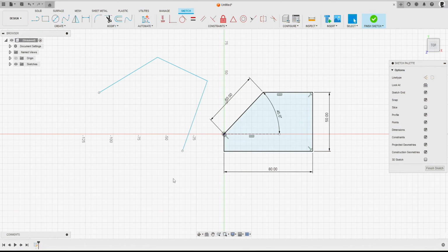And now we're no longer drawing lines from the endpoint here, so escape on the keyboard, and we've completed that sketch there. If we ever want to remove any entities, quite simply we can left click, press delete on the keyboard. We can also select them as well. If we hold down the left mouse button and drag across a line, you need to make sure that the entire line is encapsulated within the square. We're going to hit delete on the keyboard.